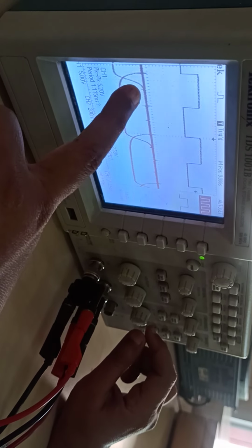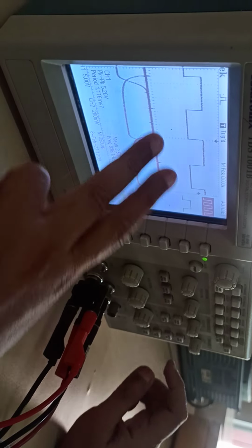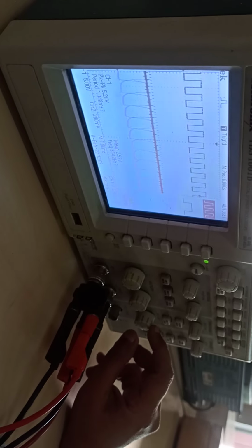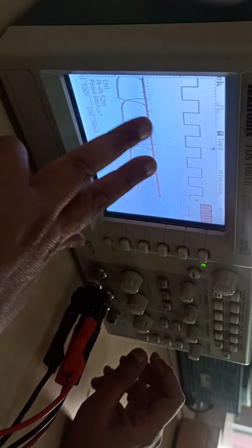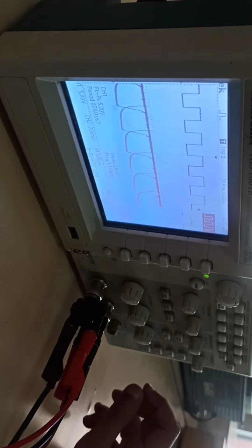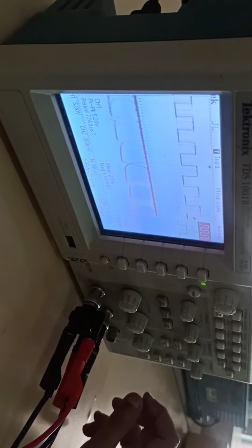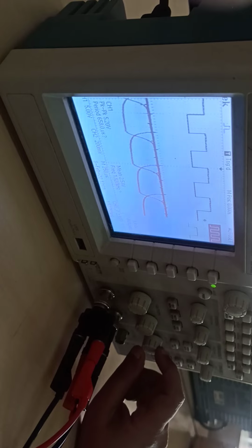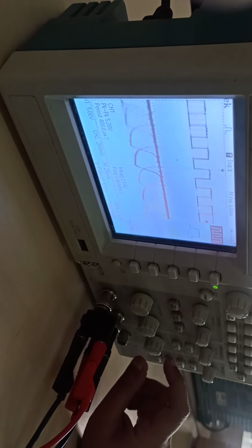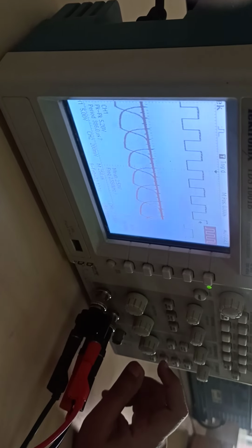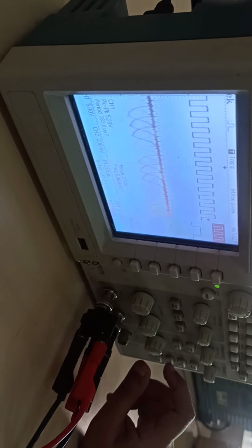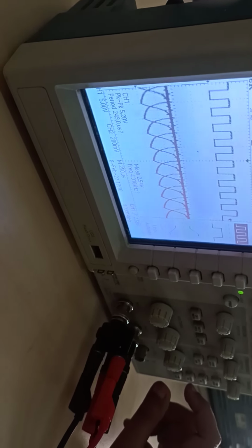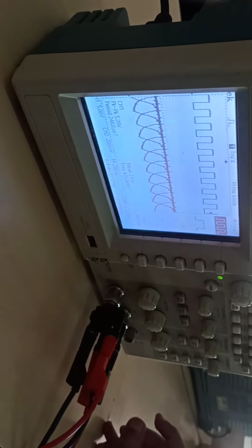This frequency has to be changed till this frequency point where the eye is closed. How will you understand the eye is closed? As I change the frequency, see, your waveform is going to change. These 2 points will come together. Now I am changing. At one point this eye will be closed. Continuously I am measuring it. So this closing point I am getting as 4.01 kilohertz.